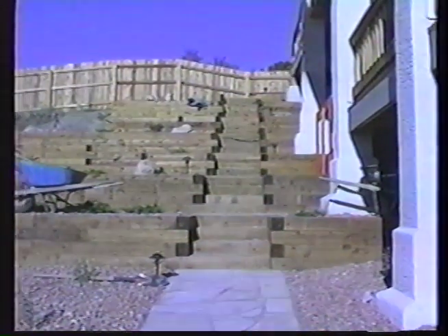Continue building the wall. If you had to step up the base course, we'll start there. If not, we'll start at one end of the base course. Align the timber for the 3/4-inch setback and overlap the joint below. Next, toenail it to the timbers below with 6-inch spikes.